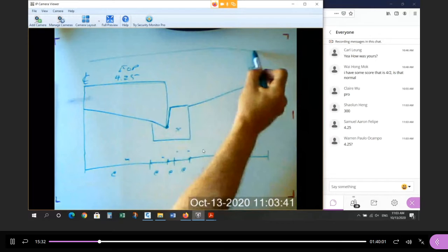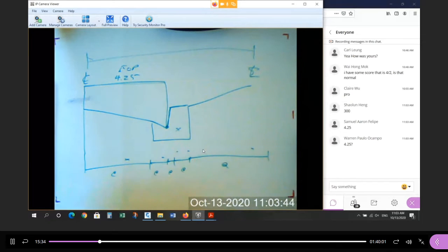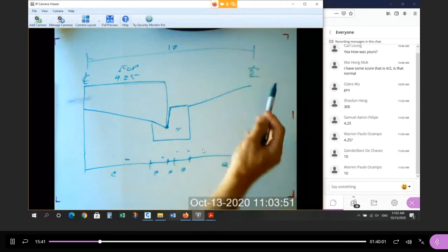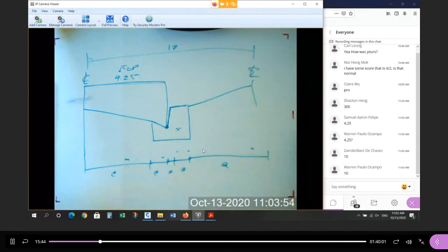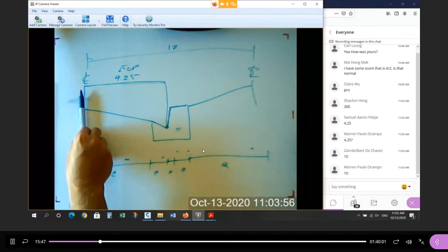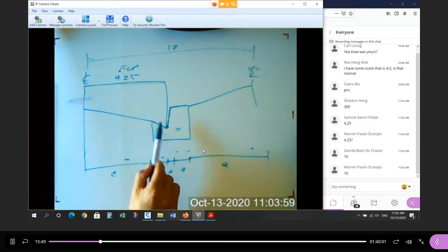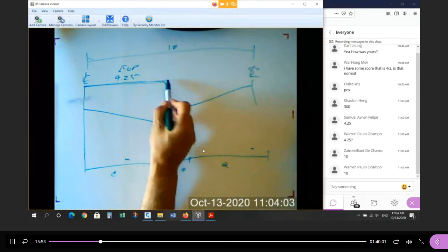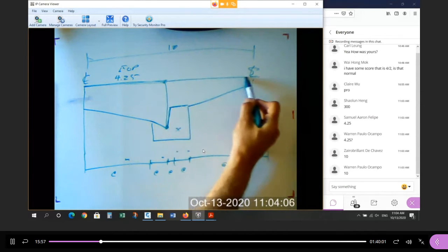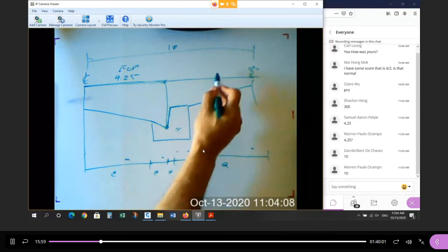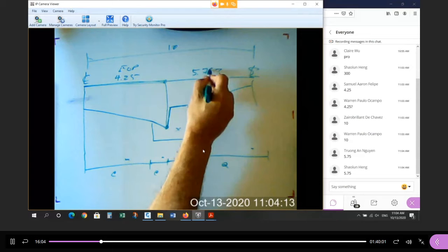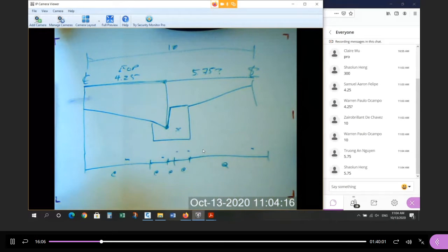If the entire right-of-way was 20 meters, how wide is half of it? So this is 10 meters. That was the offset from the street line to the center to begin with, right? So we offset 10, and then we offset 4.25 on both sides. That's how we drew our edge of pavement. So if this is 4.25, how do I get from the gutter to the street line? What's this dimension here? That's right, 5.75.